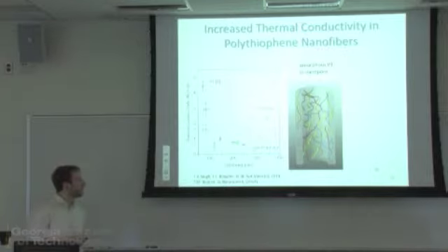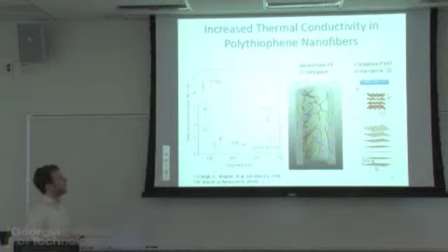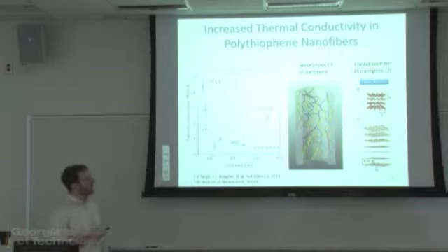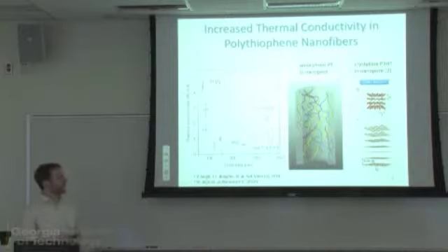Okay, very good. But so there's a different trend with P3HT. When we looked at our fibers with X-ray diffraction, we saw no crystalline pattern, so they looked completely amorphous. Then we used polarized infrared absorption, and we noticed that there is a degree of chain alignment in the tube axis. So we hypothesized that while there's some general order in the tube direction, there's no actual crystallinity or long-range order.